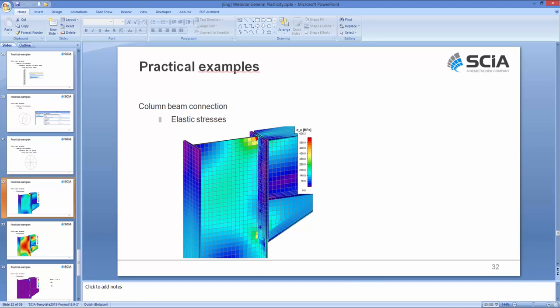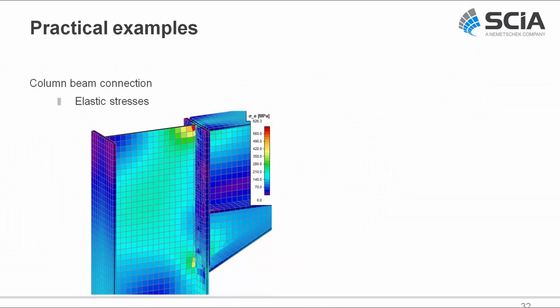If we have a look at the results again in our PowerPoint, first of all, in this PowerPoint the results for the maximal load, or the highest load, are shown. So for the last nonlinear combination, we see that our elastic stress was equal to 626 megapascal, so really too high.